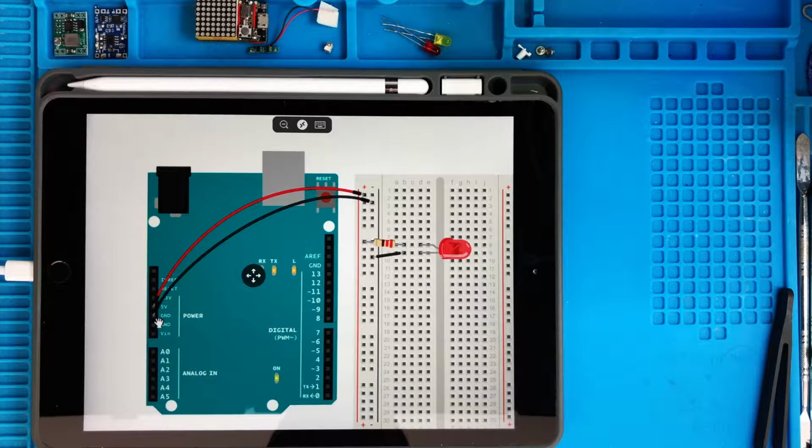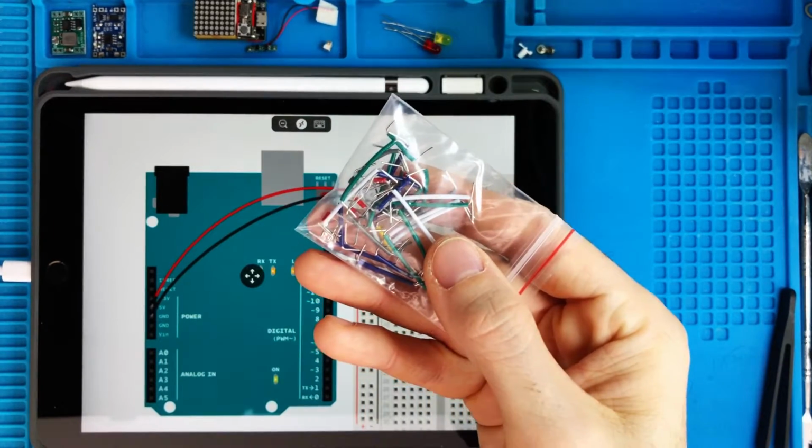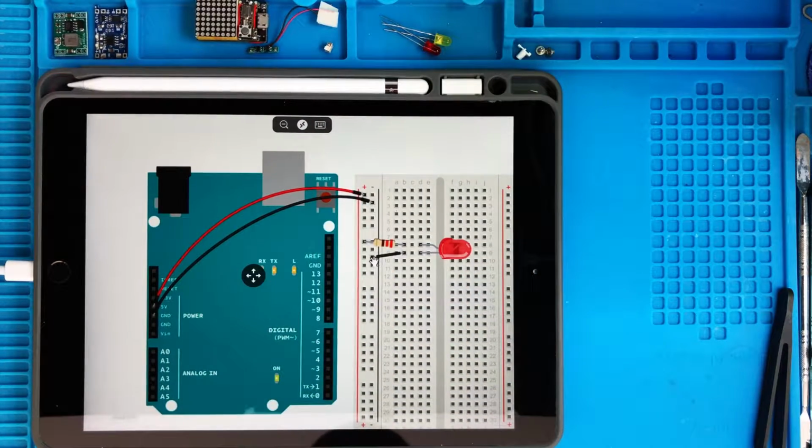So in this schematic diagram, it tells you, for instance, to connect the black wire to this minus thing. So this is connected internally with a little bridge that you can find in these envelopes here. You put one terminal here, the other here, so you connect with the terminal of the LED. Then the current flows like this. It goes inside this resistor.